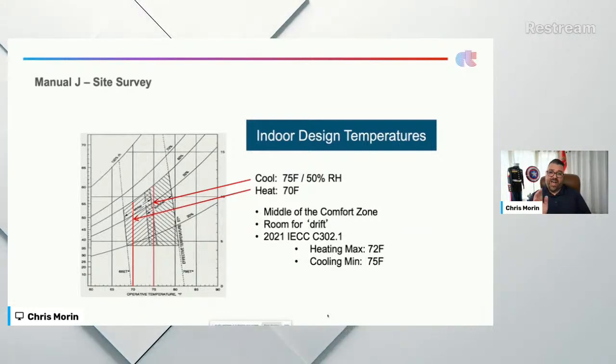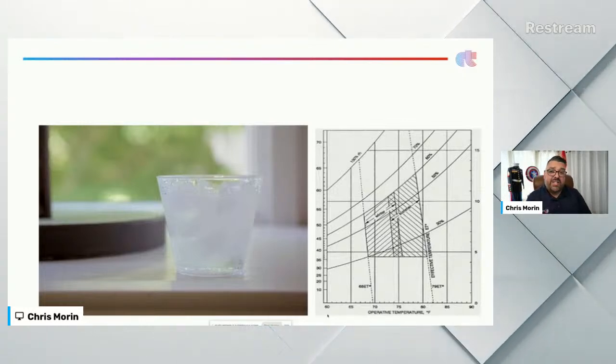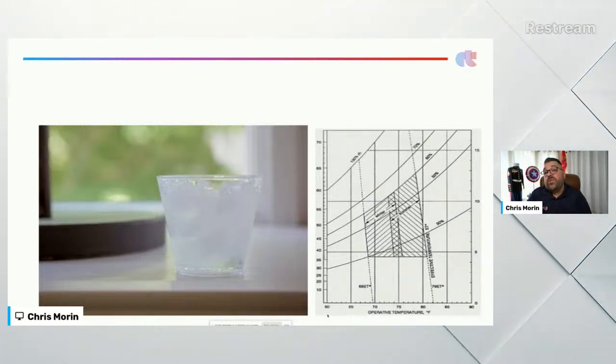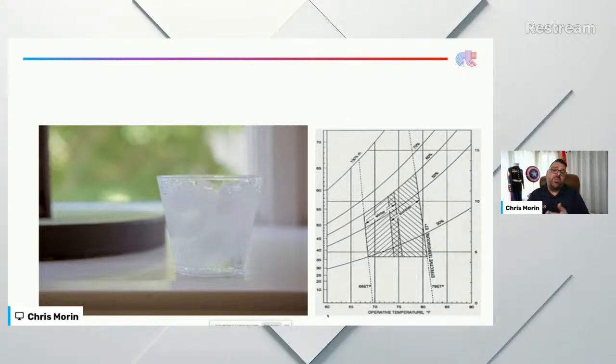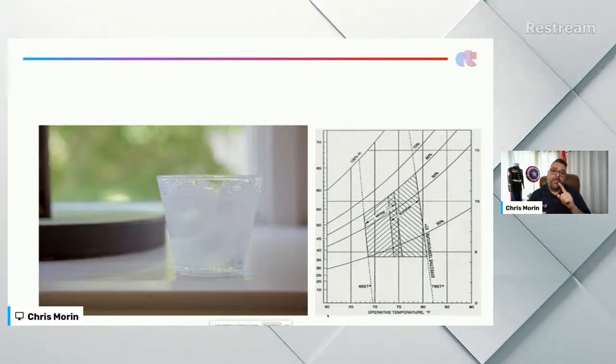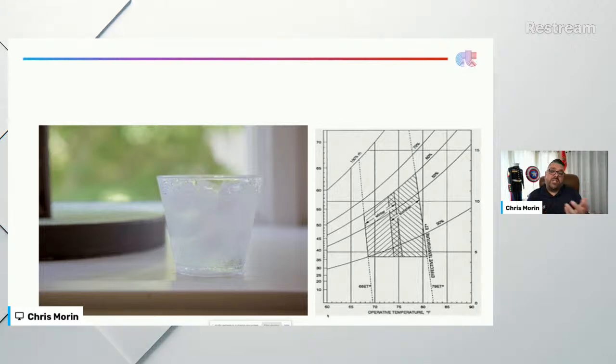But I always like to say, what happens if a customer wants to still cool to 68? Well, guess what? 67 degrees on the typical refrigerant system, you're talking 410A, A2L refrigerants that are coming out. At 67 or less on a ducted system, the coil starts to freeze because we need a temperature difference across that coil in order to cool the air. Now the temperature difference the coil gets so low temperature-wise that moisture freezes, okay? So that's number one, mechanical issues.